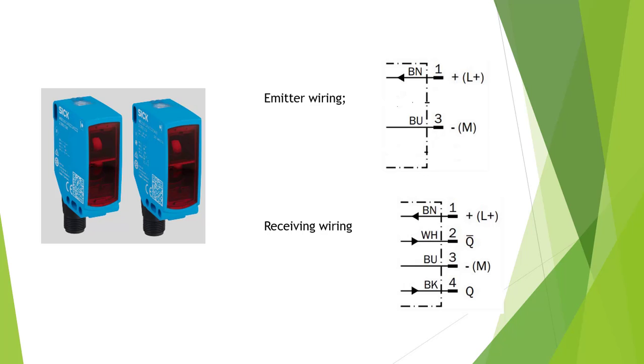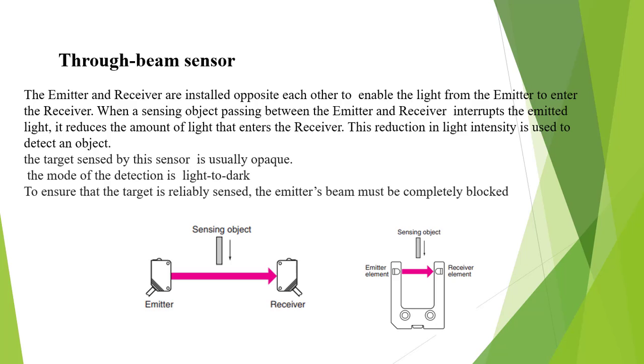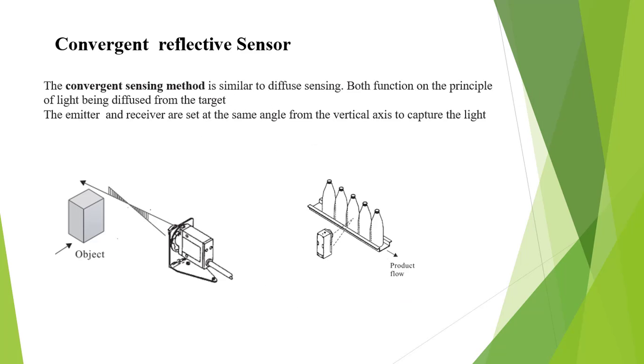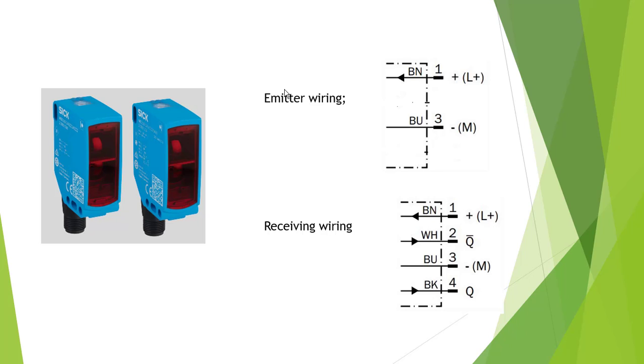Today we just talk about the photoelectric sensor. It's basic information. We often use this in manufacturing, and in conveyor systems. Just remember it's light on, dark on. The wiring is brown, blue, white, black, all the same as the proximity sensor. Okay, thank you very much.